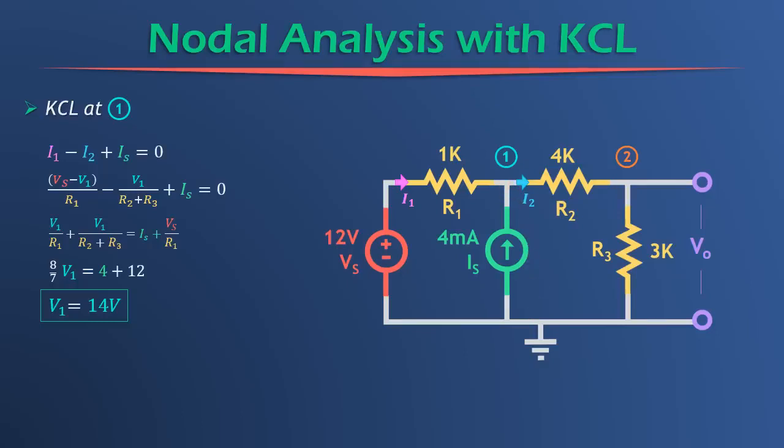And so now how can we find the voltage at V2? If we have the voltage up here, and we have these two resistors in series, how could we do it? Of course, we're going to use the voltage divider equation, because this is a voltage divider. We have two resistors in series. We can pluck off the voltage across that second resistor by using the voltage divider equation. So that is super simple.